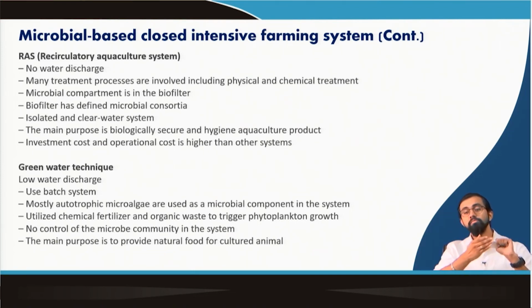Primary treatment majorly consists of filtering operations, filtering all the suspended solids present in your aquaculture wastewater. How is it done? We use drum filters, screens and different kinds of filtering mechanisms accordingly. Using these filters, we try to get rid of all the suspended solids present in your system. That is the first process.